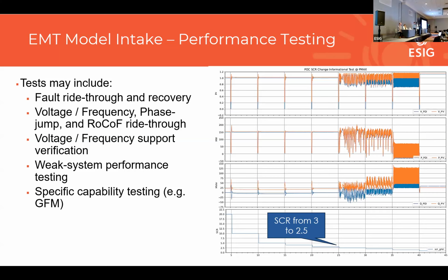And then another thing that we can do at this model intake performance testing phase is, if there's specific capability that we are looking for from the devices, it's very useful to test for that capability at this phase. So if you're looking for capabilities such as grid forming inside of your battery inverters or whatever, then this would be the phase at which you test that capability.